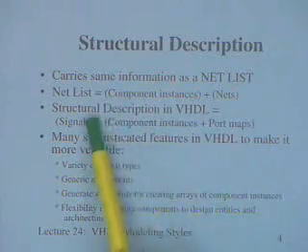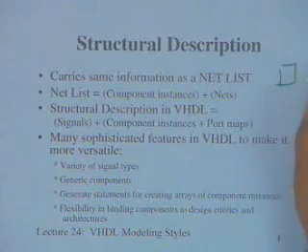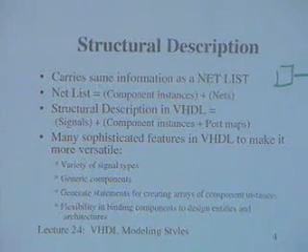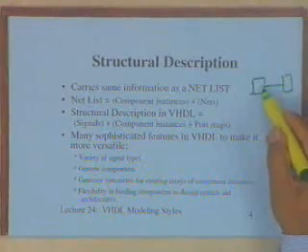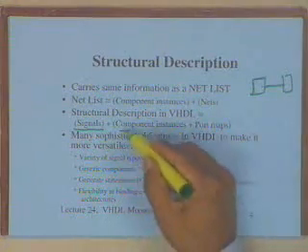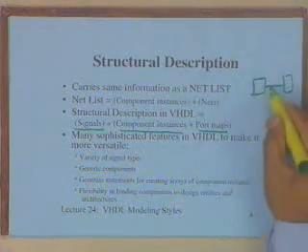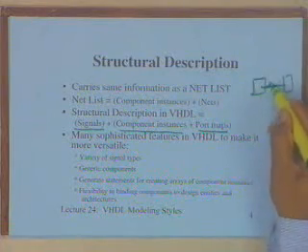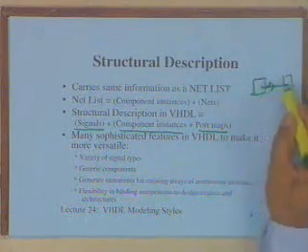On top of this, what you require in VHDL is that the connections are made. So you have one component and you have another component. The connection is made through a signal, because, as I said before, what is visible outside the components, the ports, are the signals. So additionally what you need is the signals and component instances plus port maps. What a port map does is connect this signal. It says this output port is connected to this signal, and this signal is in turn connected to this input port. The signal acts as the connection between them.